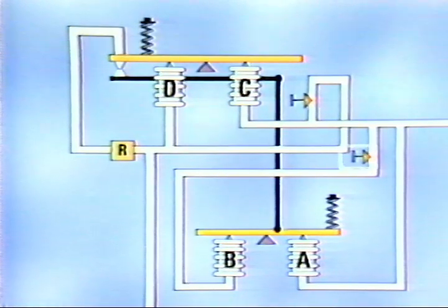Input also bleeds from the derivative time adjustment here into the B bellows, which exerts a force on this beam opposite to that of the A bellows. This would cause the flapper to move away from the nozzle. When the input to the controller stopped changing, pressures to the A and C bellows would also stop changing, signifying that the controller's rate action has stopped.